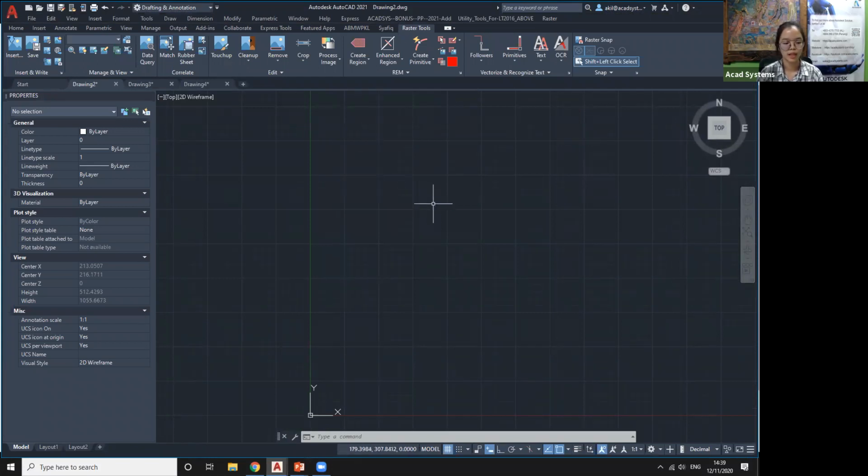When you install AutoCAD Raster Design, it will create a new ribbon item in AutoCAD here, so we can access the raster design commands and features. Now we can use the insert tool located on the far left of the ribbon. Then you can navigate to the image that is to be brought into the drawing. The command for this insert is IINSERT, and then you can click enter.